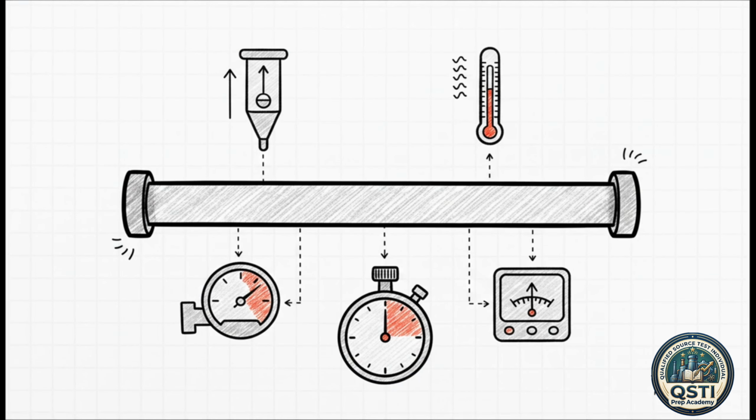Okay, so what gear do we actually need to make these measurements accurately? Grab a pen, because knowing your equipment tolerances is a massive target for exam questions. First, your critical tools start with a gas metering device. Think a rotameter, an orifice plate, or something similar. This device absolutely must be capable of measuring the stack flow rate to within plus or minus 5%.